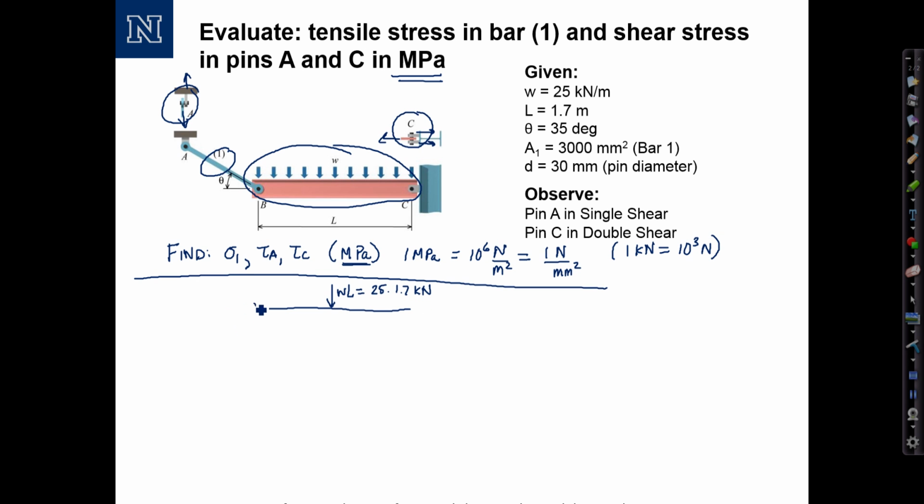I will draw my unknown force in member 1, which I'm going to label F1, and I will draw the reaction at C, which has components C sub x and C sub y. Okay, so there's my free body diagram and everything I need to consider. Not showing the lengths, but we can easily infer them from above.